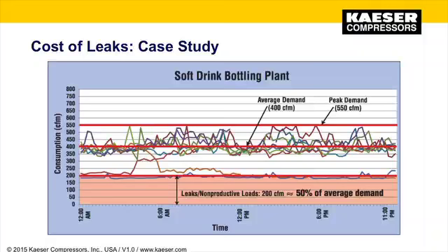In this example, a soft drink bottling company performed a leak detection audit, and they found that 200 CFM, half of their average demand, was wasted to leaks and cost them $34,000 annually.